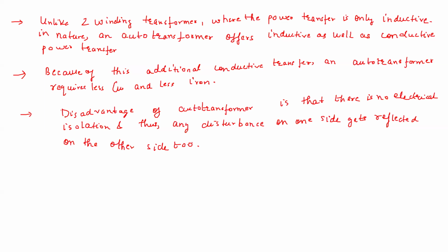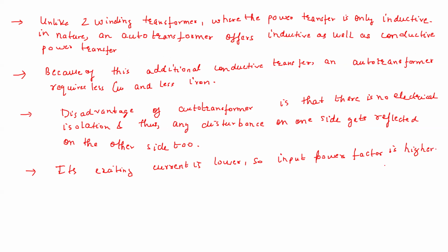Then what else have we discussed? Another thing is that the auto transformer's exciting current is lower. So the magnetizing current requirement, the exciting current requirement, is lower, and therefore its input power factor is higher. Because the no load current requirement is less, the input no load power factor is higher. Since it has only one winding and a smaller core,